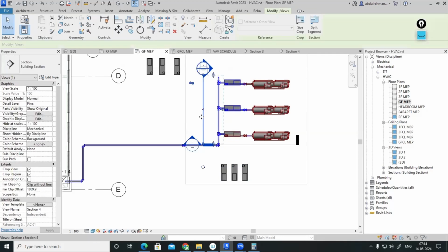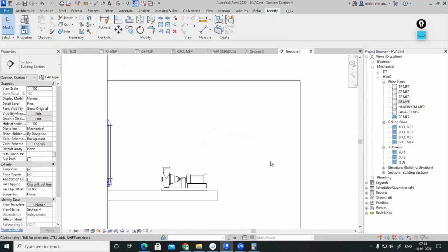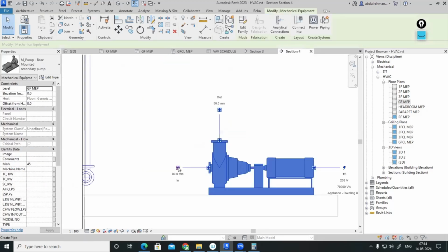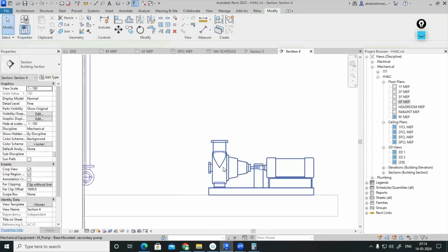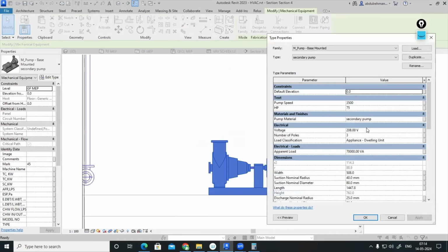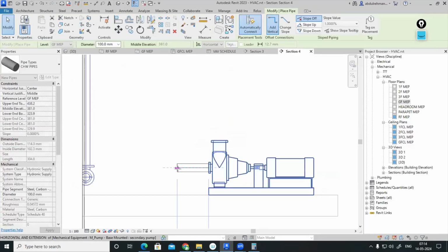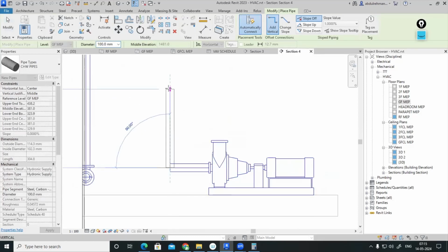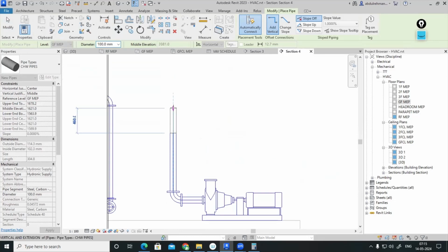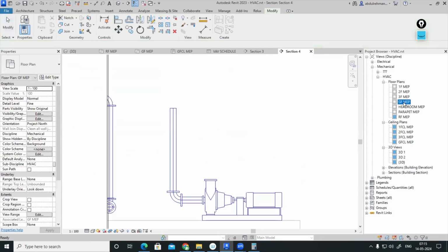Okay. So let me make the secondary suction. Secondary pump, secondary suction only, but we have to change the diameter. Both I'll be making into suction or discharge 100 mm, 100 mm for time being. But see, design is separate. I'm doing just modeling. At the time of design, you have to correct all these things. Okay. This is suction header only. I'll be slightly increasing upside.